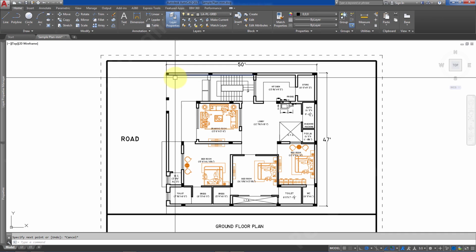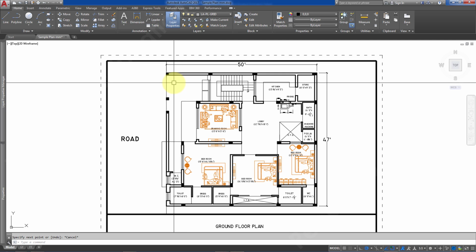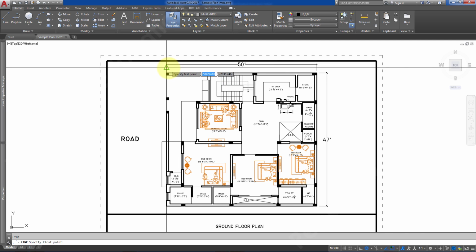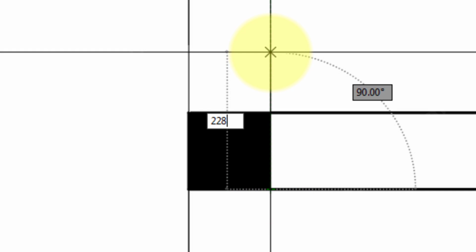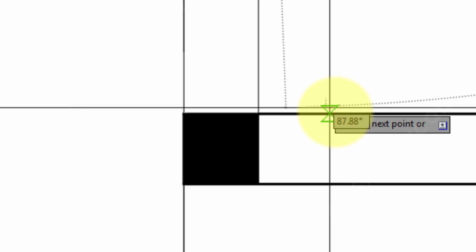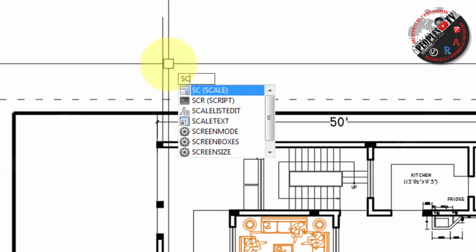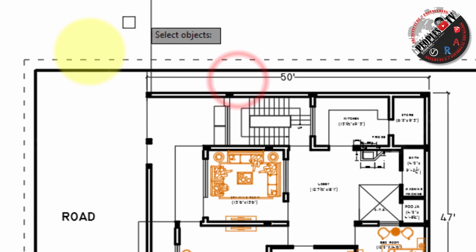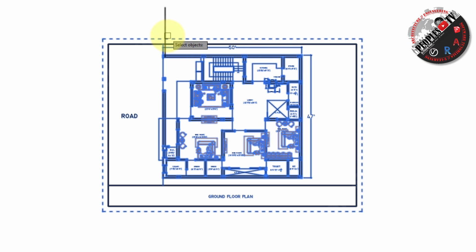So 1 inch equals to 25.4 mm and 9 inch will be 228.6 mm. So I will make a line of 228.6 mm from the edge of current width of wall. You can do that anywhere in the plan where walls are 9 inch. Our line is ready. Now I will activate scale command. Select the whole drawing except the new line I just made.